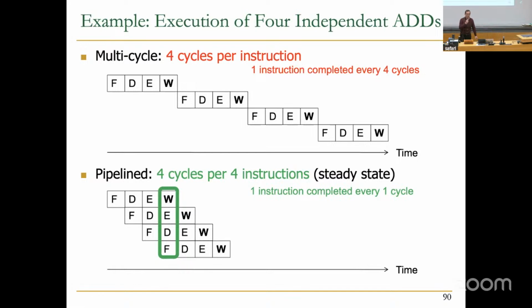So it improves your throughput. It improves your execution time in this case, and you can calculate the execution time improvement. Here it's 16 cycles. Here it's 4, 5, 6, 7 cycles, right? Okay? So it improves your instruction throughput, it improves your execution time. It doesn't improve the latency of a single instruction. A single instruction still takes the same amount of time, as you can see, right?